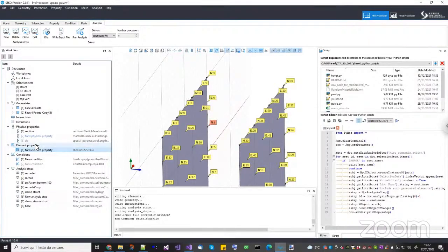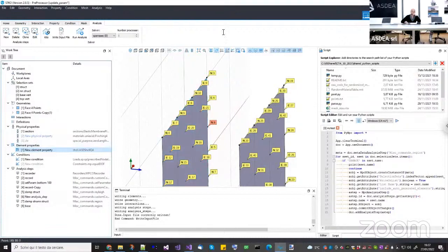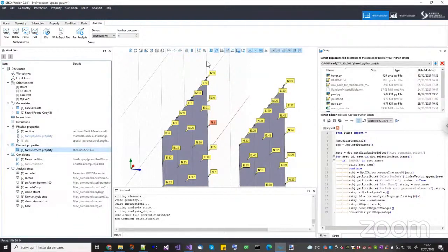Okay, thank you. My second question is regarding the RC joint 3D material. There it is written that LX, LY should be in local coordinates. But at a particular joint, there are elements from each, and each element has its own local axis. So which local axis is it talking about?